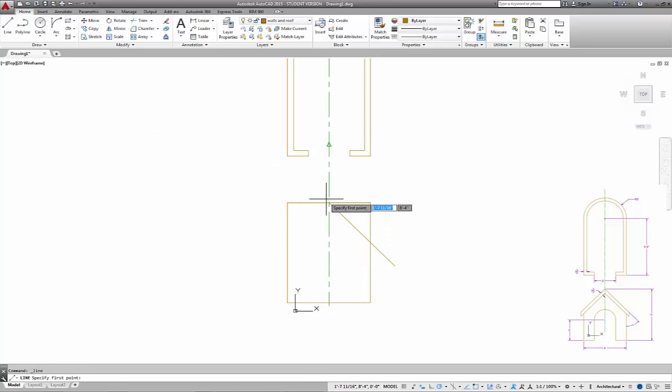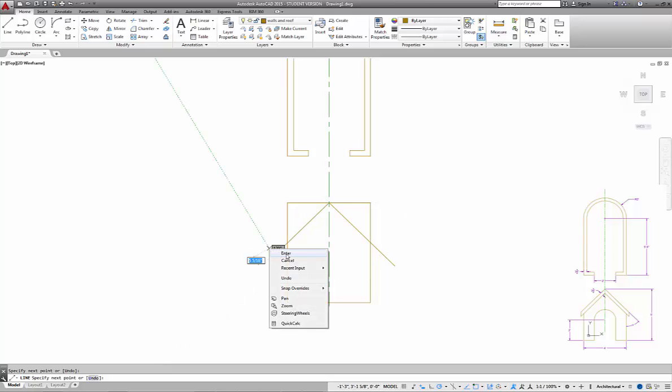So we'll pick the line command and we'll draw a 45 degree angle. It says 135 degrees. That's okay too. 225 plus 45 is 270. Okay, so that gets us the angle that we want to work with. And again, we're going to make this extra long, longer than we actually need. So that's the roof of the house.